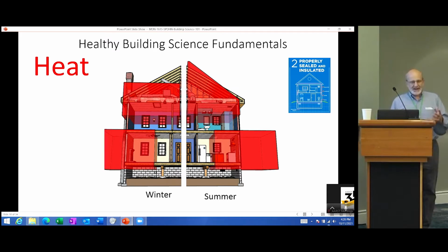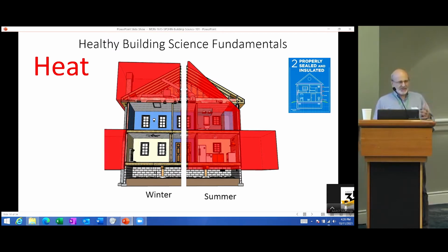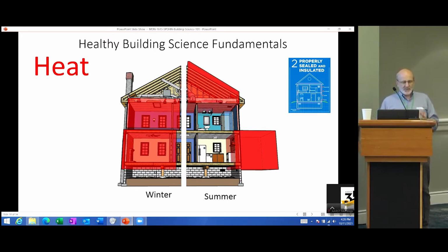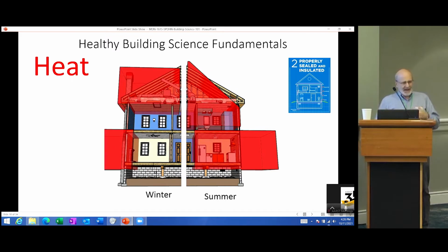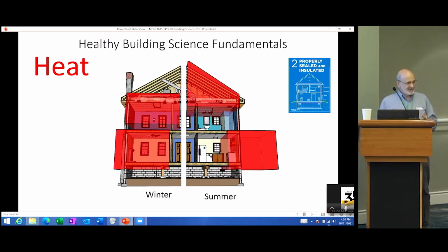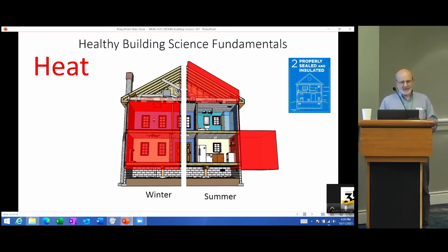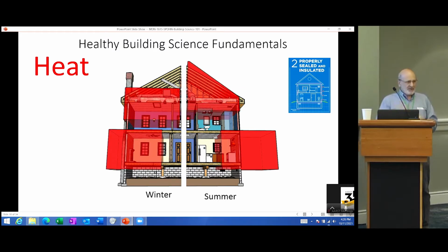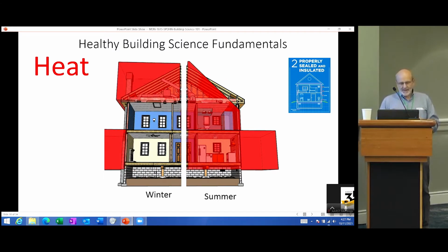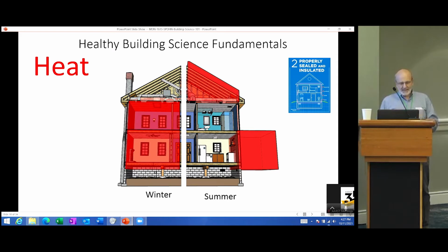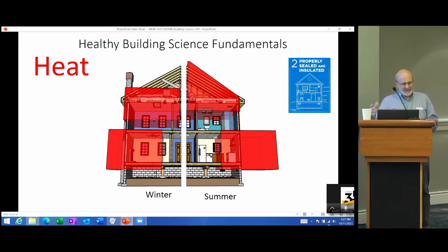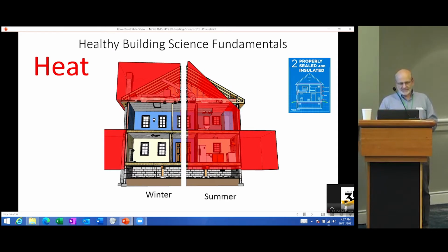But when it comes to a house, this heat movement can also cause air movement. So in the wintertime, heat moving outside of the structure can cause a stack effect to move air, and whatever is within the air, through those internal and external pathways. And in the summertime, it can be the opposite direction, with heat moving towards the cold.